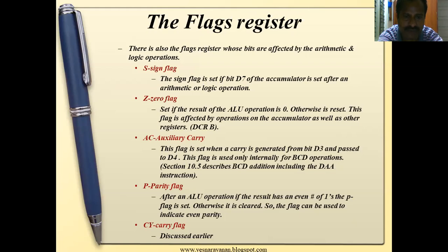After an ALU operation, if the result has an even number of ones, the parity flag is set. Otherwise, it is cleared. So, the flag can be used to indicate even parity. Carry flag. The carry flag is set whenever a carry appears when an arithmetic or logical operation is performed by the ALU.